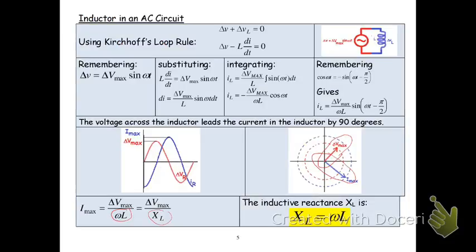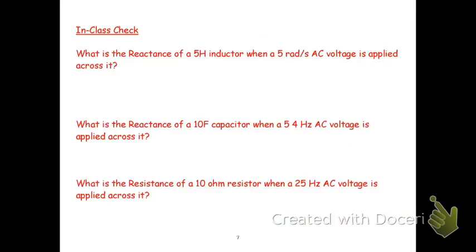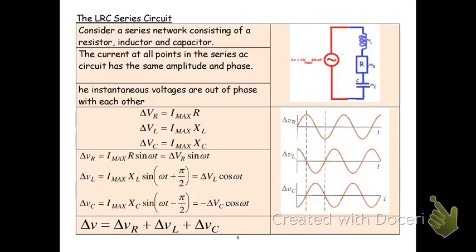They're pointing in different directions. So I can't just arithmetically add them up. I've got to vectorially add them up. And in doing the vectorial addition, I find that the voltage drop across the L is directly opposite in terms of the sign, the positive and the negative. It's in the opposite sense of the voltage across the capacitance. So they're fighting each other.